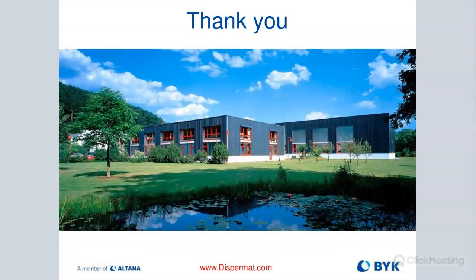You would absolutely see it in the application process when you are, let's say, spraying out a panel and you no longer have good flake orientation, or instead of being silver it looks gray, or you're not getting the right color. That usually is indicative of an issue with your particles. So application parameters as well as an electron microscope can identify if something has gone wrong.